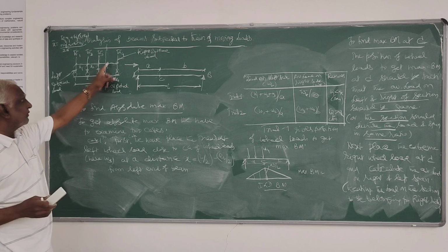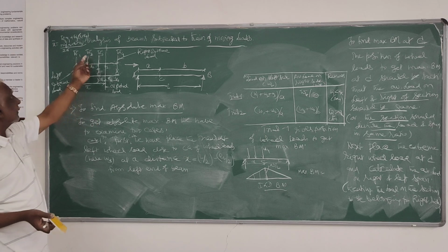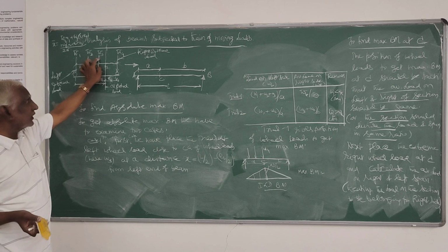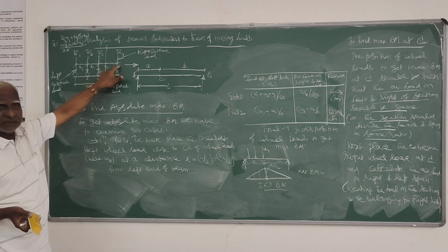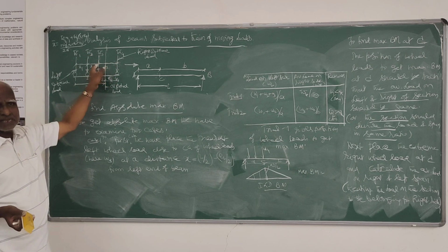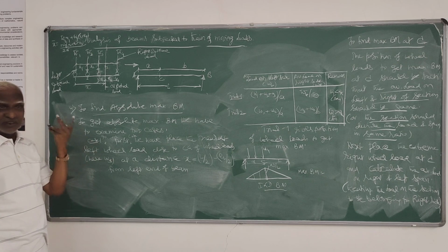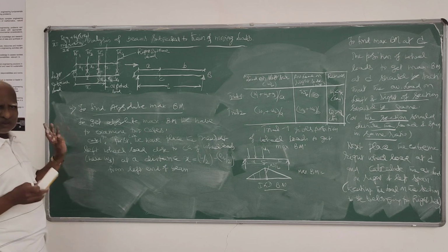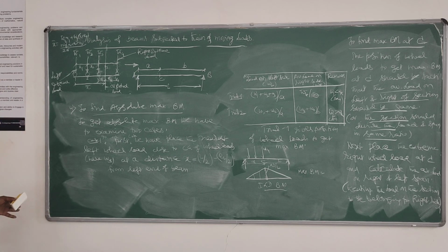Otherwise, sometimes you can take whichever is closer and whichever is heavier out of these two. But suppose both of them are of the same magnitude, or one is smaller and one larger and the distance between them does not vary much in the position of the wheel load. In that case also we don't know, and we will be in a dilemma about under which load the maximum bending moment occurs. That is why it is better to calculate for both and work out the maximum. That's all the procedure. I hope I made things clear.